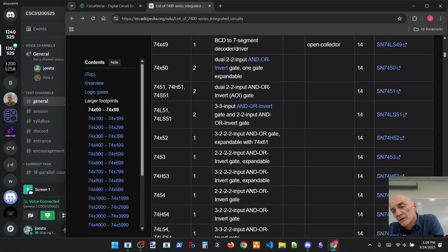So this is where I don't know if we actually built these into subcircuits, but I feel like I might have said at one point that it might be convenient to, because remember, frequently we would AND together a number of combinations. I'm thinking about our general rule for implementing any truth table. You take your inputs and you NOT each one. So we've got all the combinations there. And then we would AND together the combinations we wanted.